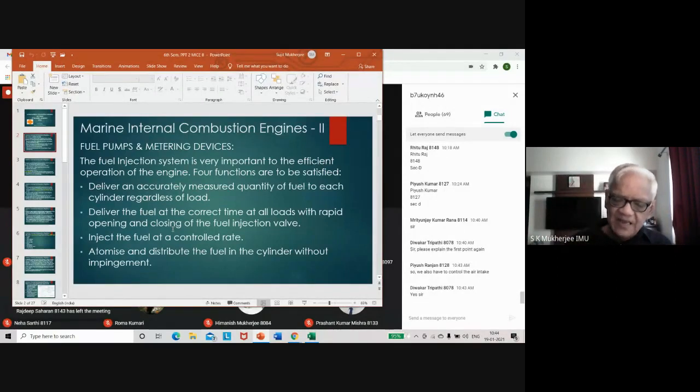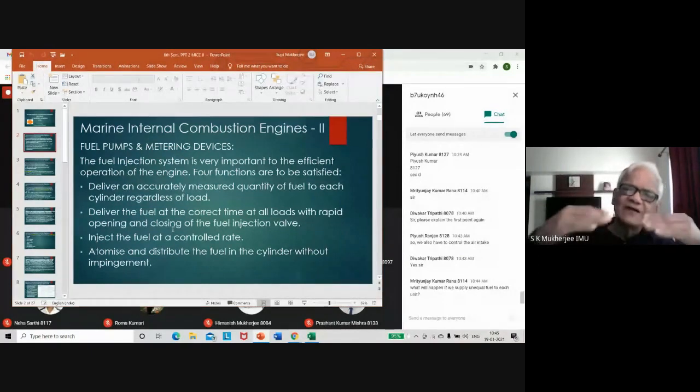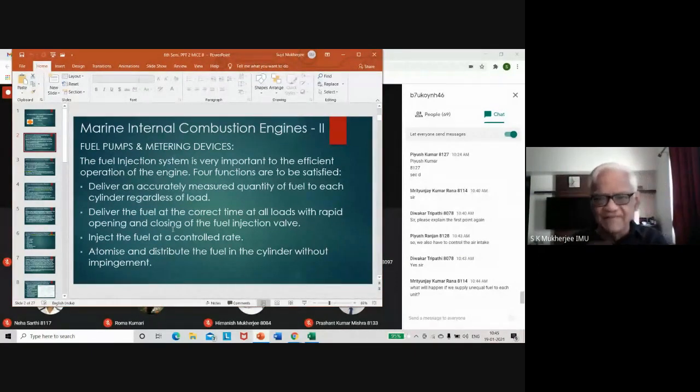Now when the engine RPM keeps increasing, of course, it has to increase slowly up to the full speed. As it keeps increasing, the discharge from the exhaust will also be increasing, so the power supply to the turbocharger will also be increasing. So if the supply to the turbocharger is increasing, then the scavenge air supply will also be increasing. So it is self-controlled. The whole process is self-controlled.